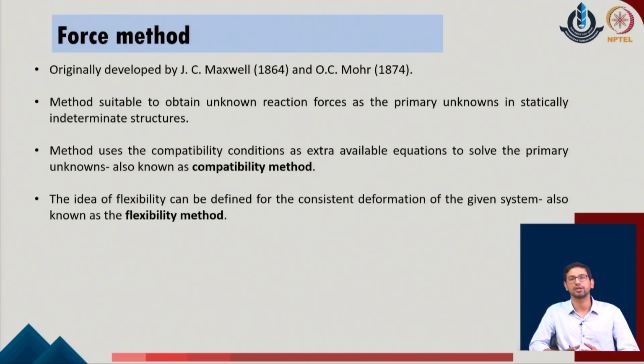The method uses the conditions of compatibility as the extra conditions to solve for these unknown redundant forces, and that is why the method is also called the compatibility method. And in the force method, when we apply it on the given systems, we typically introduce unit loads, and corresponding to that, to define the consistent deformation, we describe the condition of compatibility of the deformations. This is done by identifying the displacements due to these unit loads on the given problem.